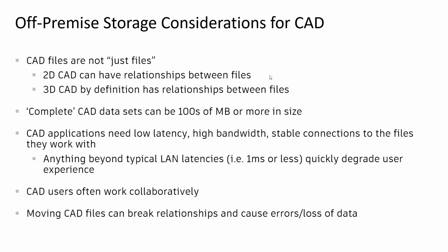If you start to work on CAD files stored on a wide area network, maybe you're getting into the 10s to 30, even 50 milliseconds of latency or more between, again, your computer and where the files are stored, the software very quickly becomes unusable. And then in a worst case scenario, if you put it on what is essentially a Windows share that happened to be stored on the cloud somewhere, you can just forget it. It's gonna take you forever to open an assembly. You're gonna end up crashing when you save. It's just gonna be a disaster, right?